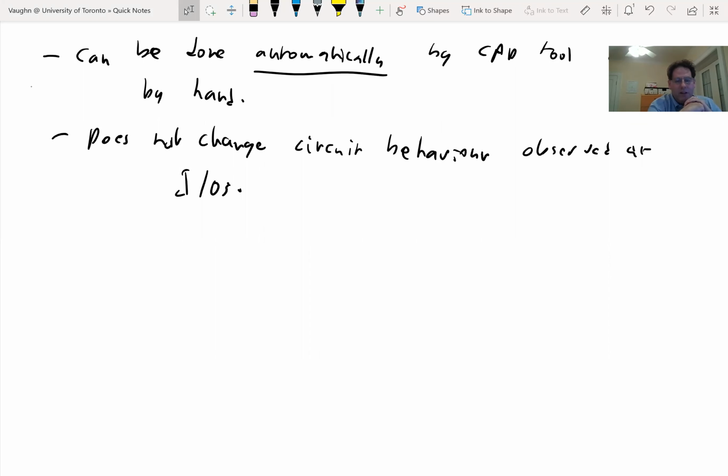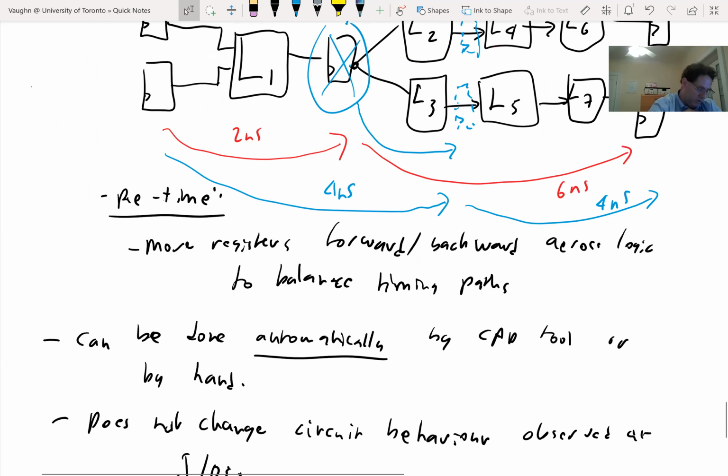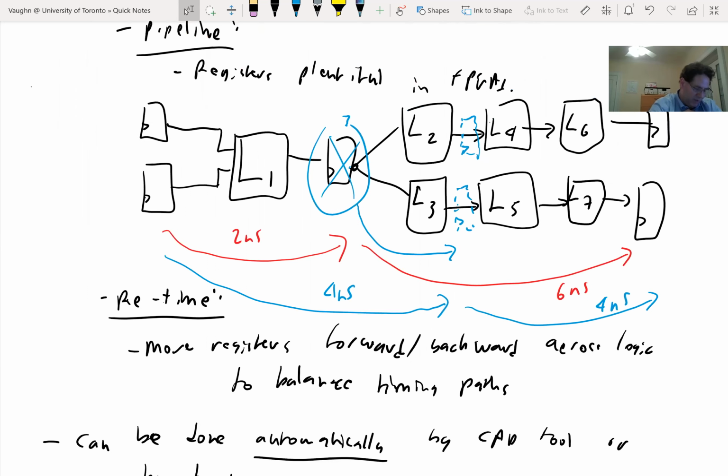It's gradually getting better, and we'll talk about this later in the course. FPGAs are also getting more and more register rich, including even putting registers in the interconnect. So it's getting more important as they do that. And a key one is harder to debug. So it also can increase area usage too. So it's also true. The example I showed you here, we retimed this register, but we made 2 copies. So there was some increase in area usage.